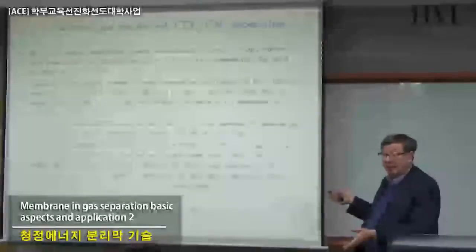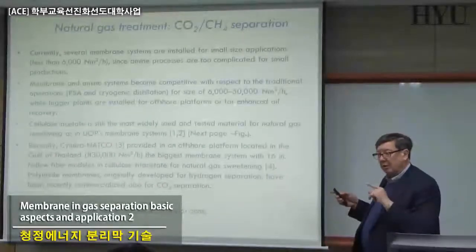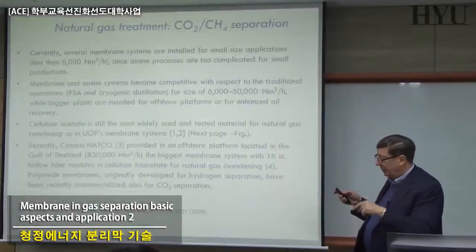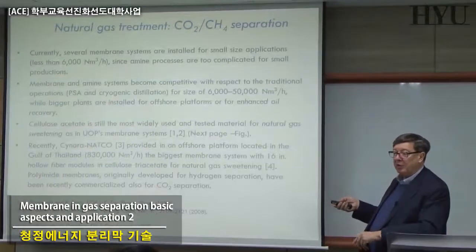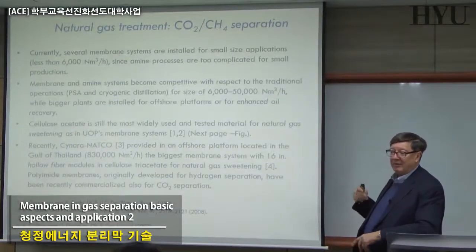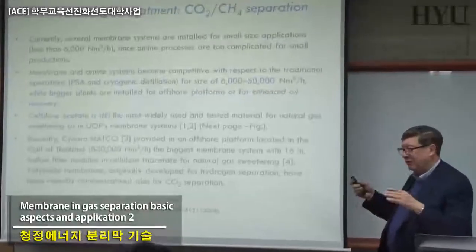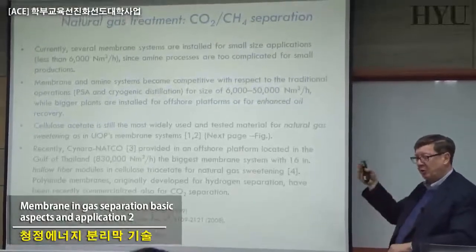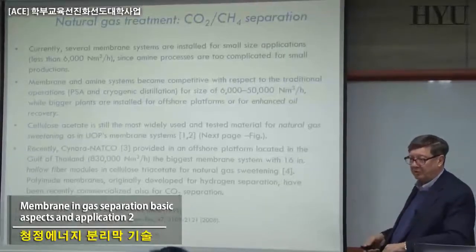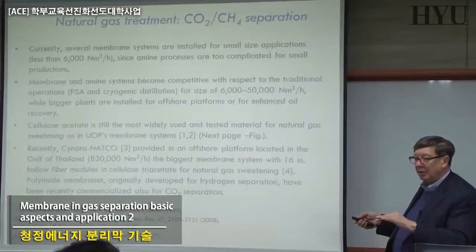That means no gas separation, because if you are using gas separation, by definition there is no water. If you measure, however, the gas separation, for example, the humidification with cellulose acetate, you will find that the nitrogen separation factor is huge. It's 400 to 1. There's a very good separation. However, you have to find a way to have this material always wet.